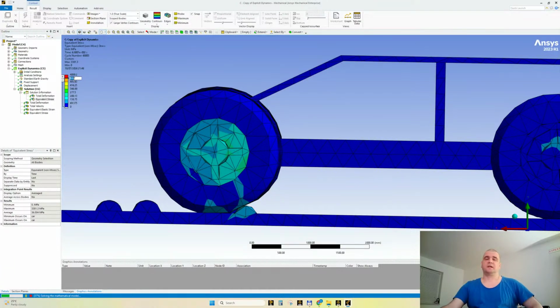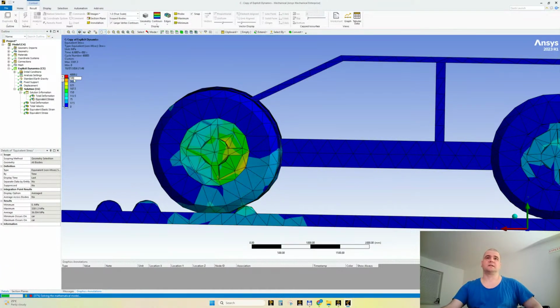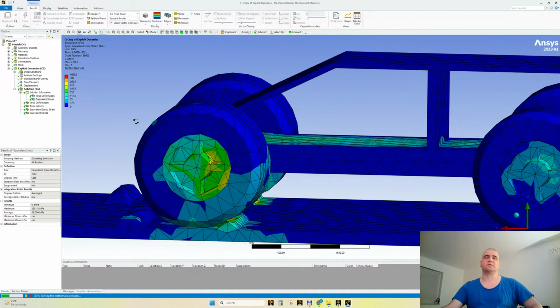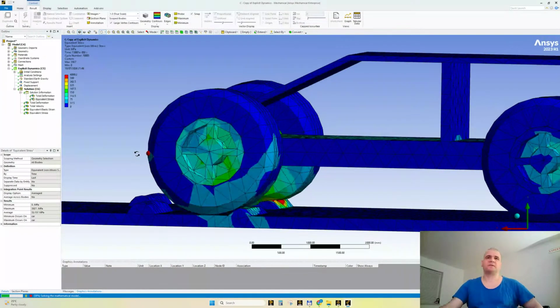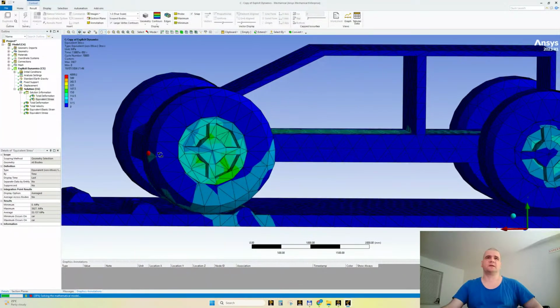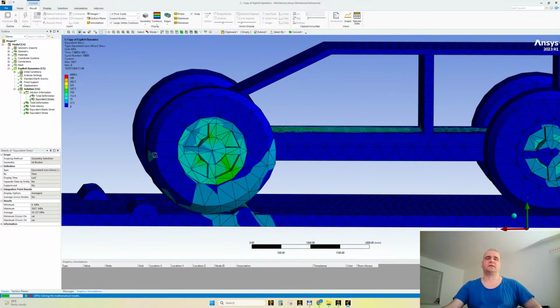A software that doesn't care too much about the mesh refinement, I mean, does not extend the solving too much, is LS-DYNA. So if possible, try and familiarize yourself with LS-DYNA, because in LS-DYNA you can use very fine meshes, and the solving time will not extend too much.